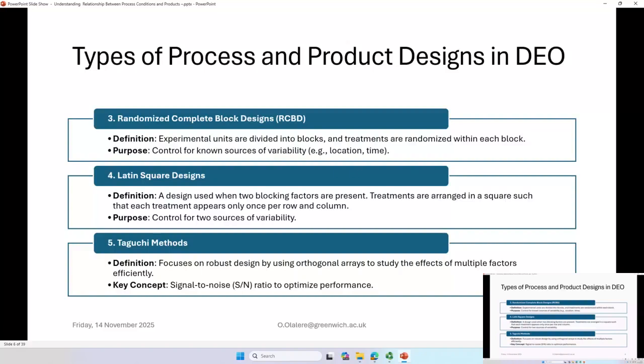What you do, you can actually use Taguchi. Taguchi is more useful in manufacturing because you don't need many experiments to arrive at the optimal condition. Even with a particular company, with 9 runs or 8 runs, you can get the optimal condition and give it to the company, saying this is better than the one we have been using before.